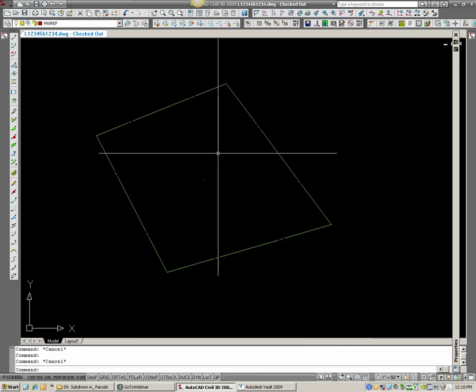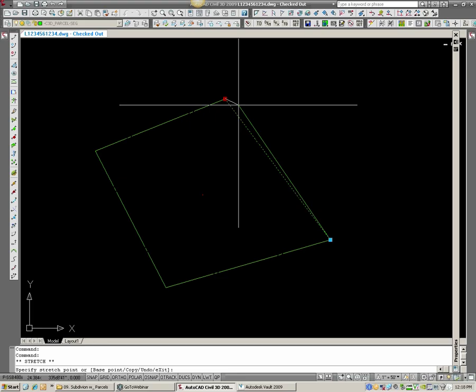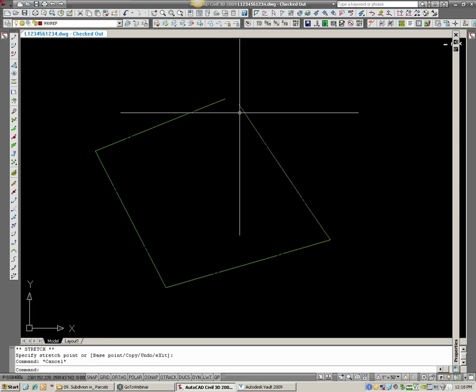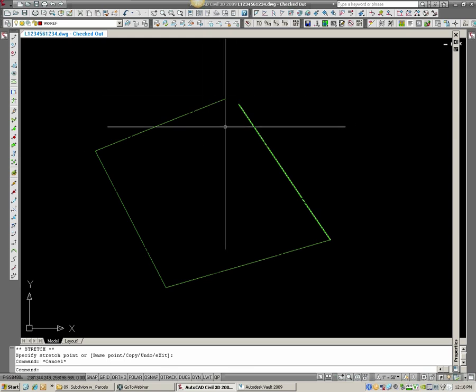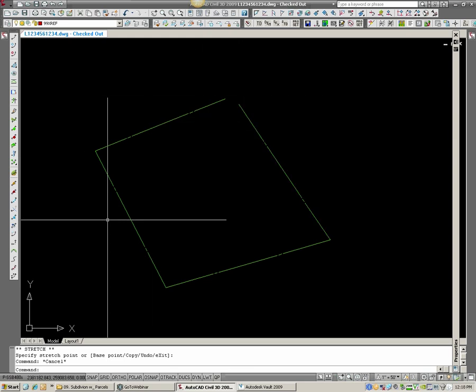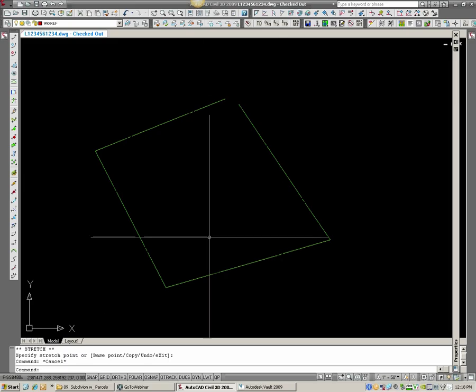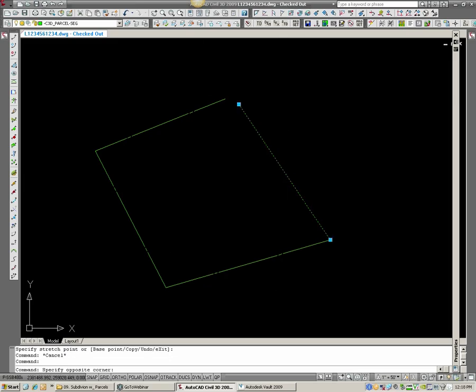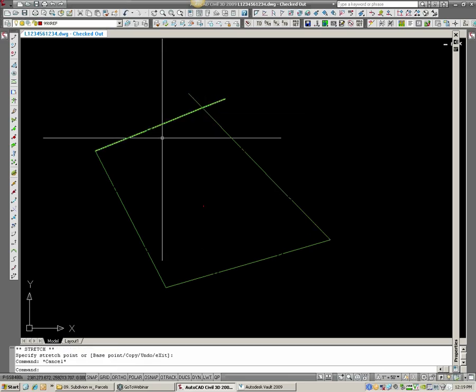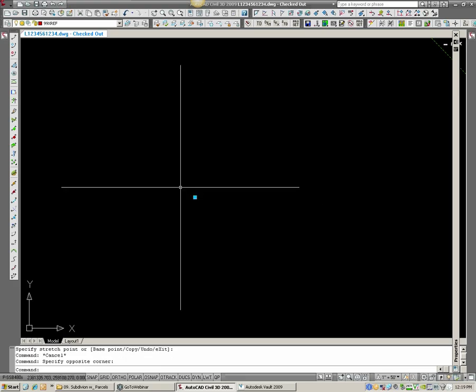Now that center dot, if I break apart my parcel segments, you'll see the center dot disappears. Well, I no longer have a parcel. Parcels must be closed. Well, how do you define a parcel? A parcel is defined by an area that is enclosed by parcel segments, these being parcel segments. So as soon as I close this again, and I don't even have to tie to endpoints, I just have to make a closed area, you'll see my little red dot show up again, being the parcel.